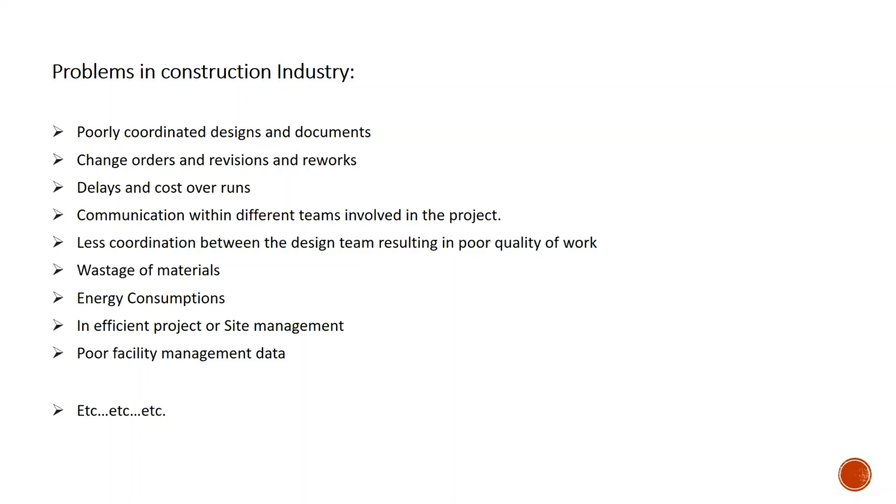Energy consumption is actually an important thing, because for a commercial project, it is mandatory that you need to have a green building certificate, or we have to check the energy efficiency. In the design stage itself, we need to perform certain analyses so that the energy consumption for that particular building will be less. We have to compare that with the ASHRAE standards, and depending upon that, we need to check how much EUI value or annual utility cost value there will be if I design the building in a particular site in this way.